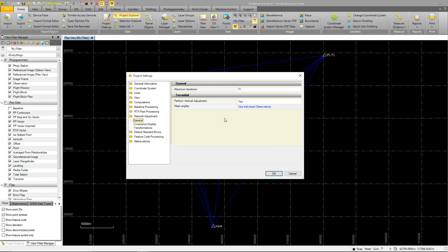If you're, for example, running total station network or observations, and you're just sighting the backsight for angle only and aren't concerned with doing the 3D measurements on your backsights, just looking at it from a 2D perspective for azimuth or for angle, you can turn off the vertical adjustment and adjust just the horizontal components of your observations and make that work.